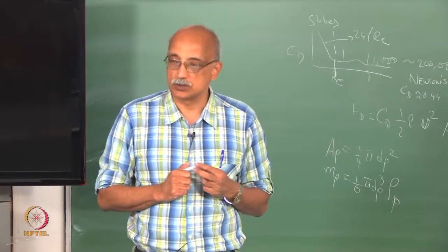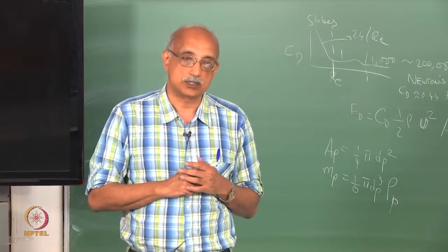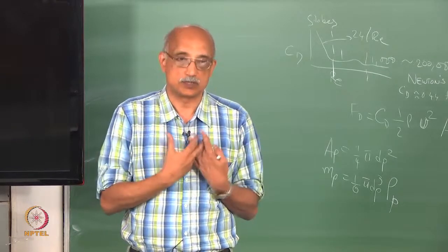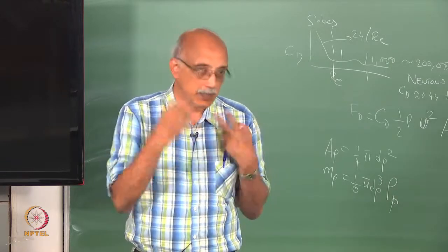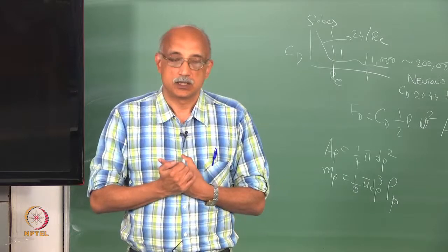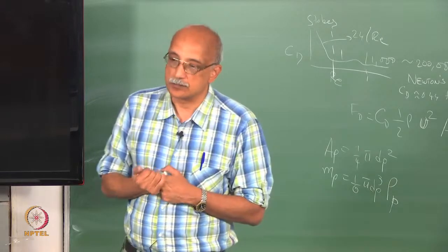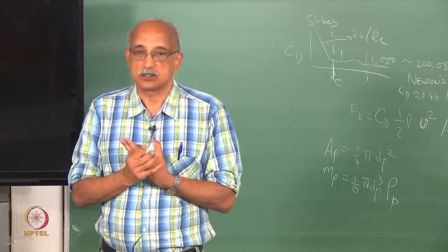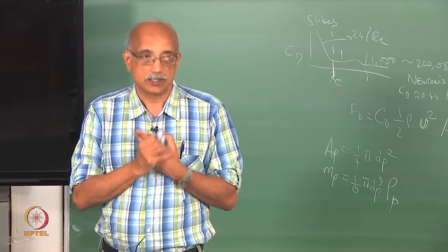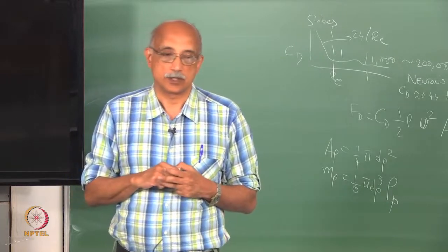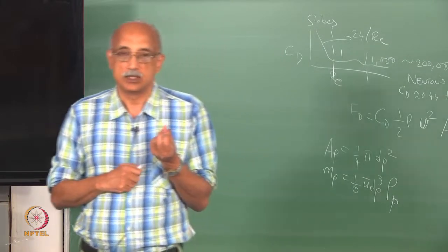So, it is very important to take that into account. Although eventually what can happen is when particles in a fine particle suspension get close enough together, they start agglomerating. So, they become larger in size and then their settling velocity increases. So, hindered settling is not something that happens monotonically. After a certain point, once the concentration of particles increases to a level where agglomeration becomes likely, then settling can again speed up.